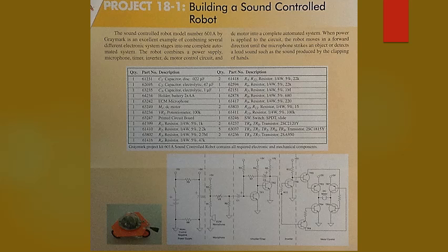And finally, you should understand the concepts and the descriptions for thyristors, what thyristors are, and the different types of thyristors, which are two: the SCR, the silicon controlled rectifier, and the triac. One of them is used for DC circuits, the other one for AC. You should know which one's used for which type of current.